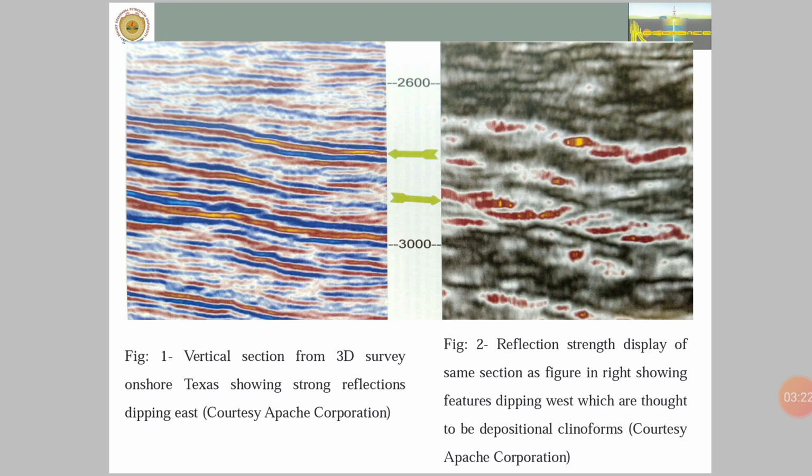The offset constraint may be evaluated by Pythagoras theorem as h equal to (x square plus y square) whole to the power half, where x is equal to length of receiver line minus source line shift. Y is the distance from the shot to last receiver, and we need to decide on the x and y roll-alongs. If we can do a good survey with a good amount of frequency required for mapping, if there is a continuity in the horizons which we would like to map, in this case the two important horizons which were of interest to us are shown by green arrows here.